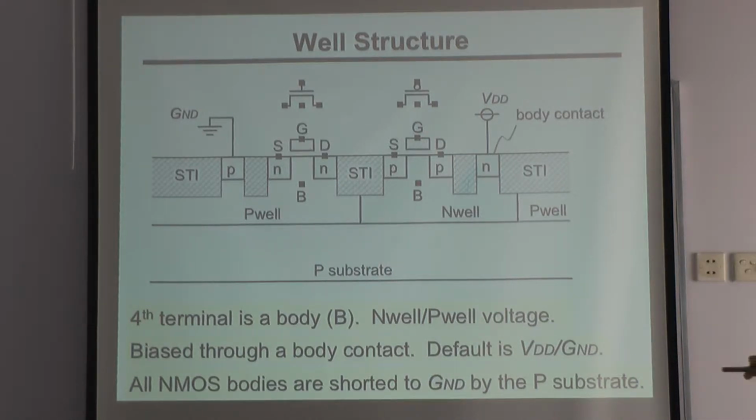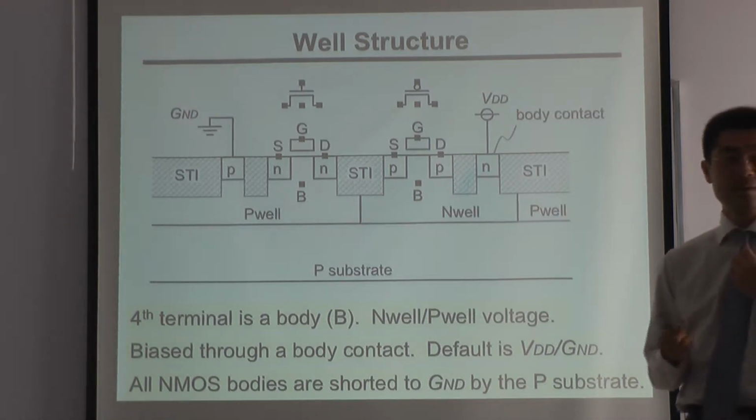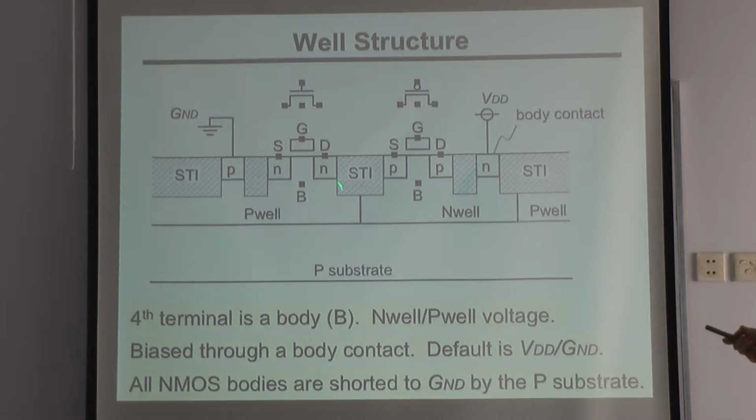In this structure, the P substrate is common to all, so all NMOS bodies should be terminated to ground.